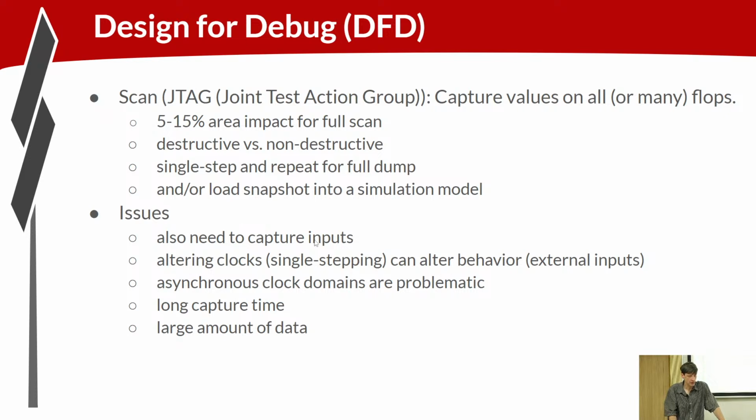So as I said, you might also need to capture inputs if they're not driven by flops that are scanned. All these things that we talked about reliability, if you're stopping execution, but there are other things that happen asynchronous to the logic that you froze, you're impacting the timing of your simulation, so you impact repeatability. Yeah, again, asynchronous clock domains.